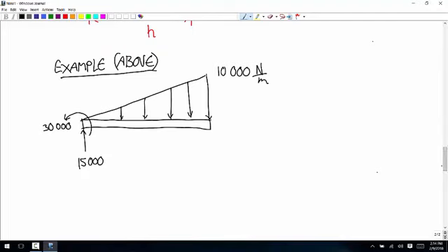So now to start doing the cuts, we have to choose where the boundaries of the subfunction are going to be. Remember that the boundaries of the subfunction will be at endpoints, so those first. And then other locations will be places where there are point forces or point couples or places where the distributed load function changes.